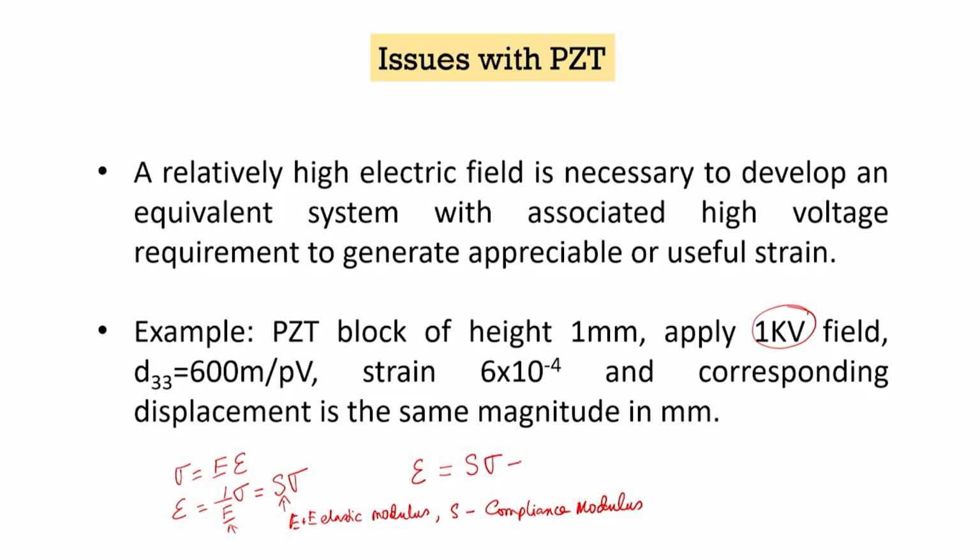But in addition to that, for a piezoelectric material there is this electromechanical coupling coefficient d times E, the electric field intensity, that can also generate the strain, that is the active strain. Now, we are going to focus on this part of the strain. So, what is the electric field intensity?